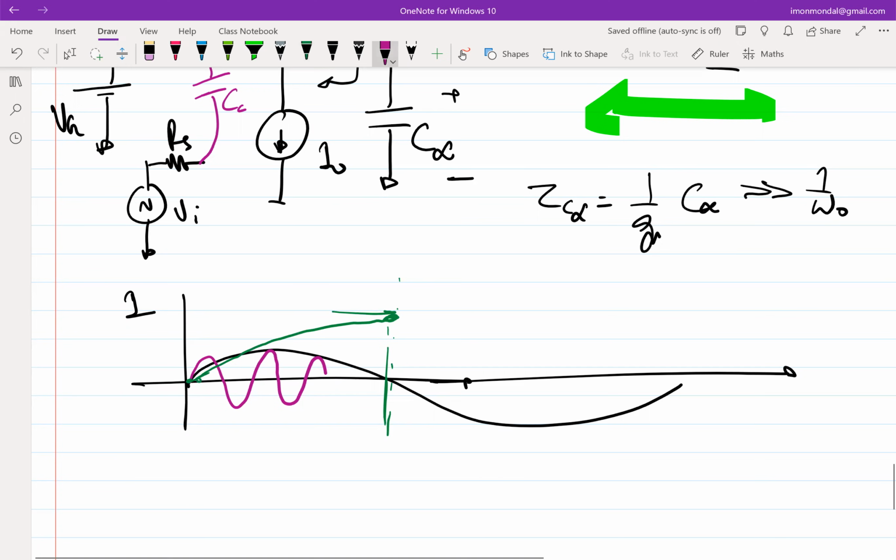But for a high frequency input, you accumulate charge for a low amount of time for the same amplitude, so you don't allow the voltage to build up. Hence the capacitor gives you low impedance at high frequencies and high impedance at low frequencies. It boils down to the integration operation.